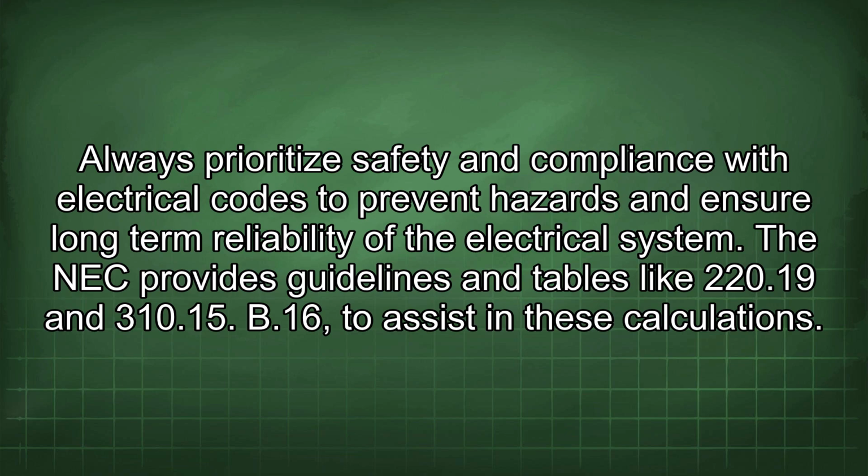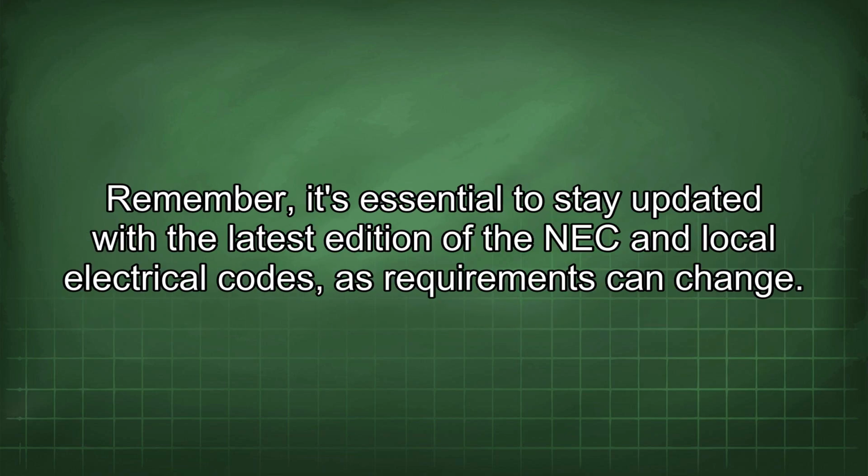The NEC provides guidelines and tables like 220.19 and 310.15(B)(16) to assist in these calculations. Remember, it's essential to stay updated with the latest edition of the NEC and local electrical codes, as requirements can change.